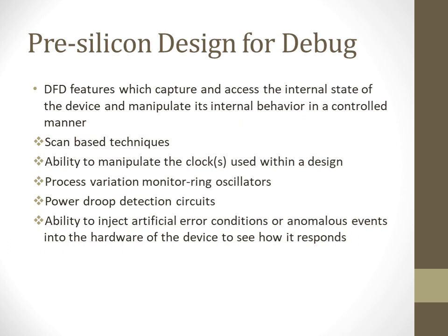The scan-based technique was taught when we took the design for testing earlier. Scan is typically implemented by connecting all the storage elements in a design, such as latches or flip-flops, together in a serial shift register, in addition to their normal parallel connection to the digital logic.